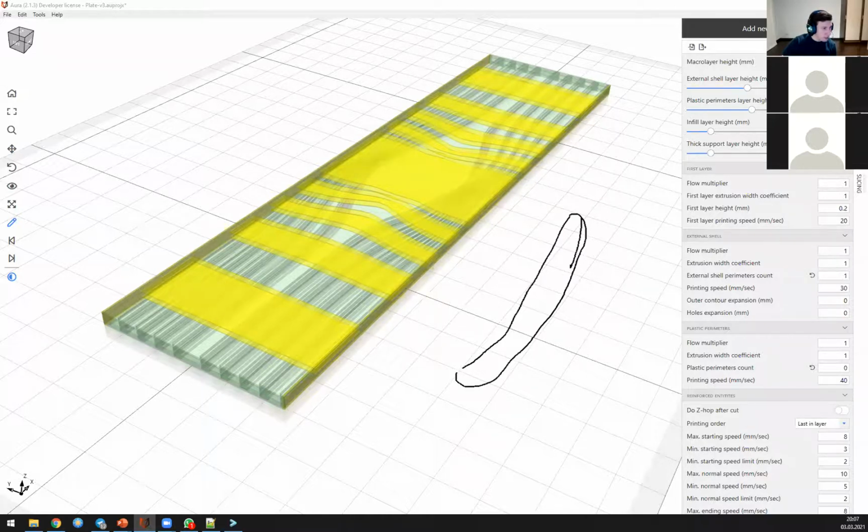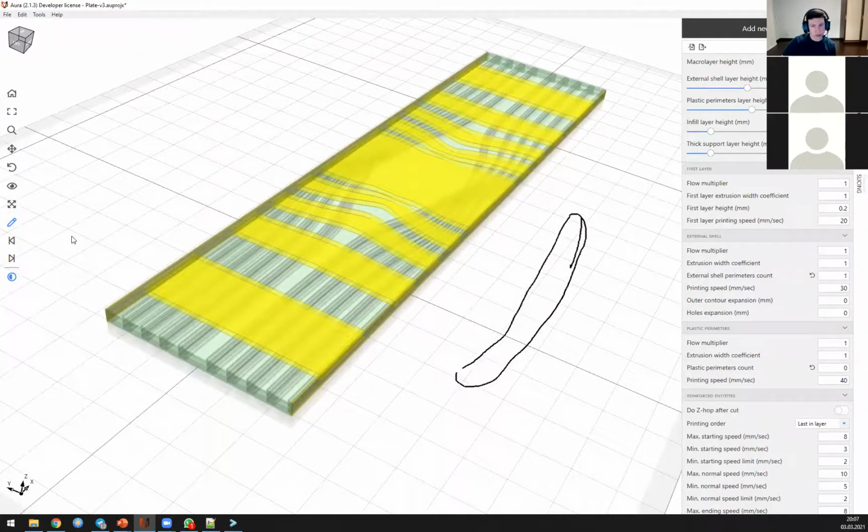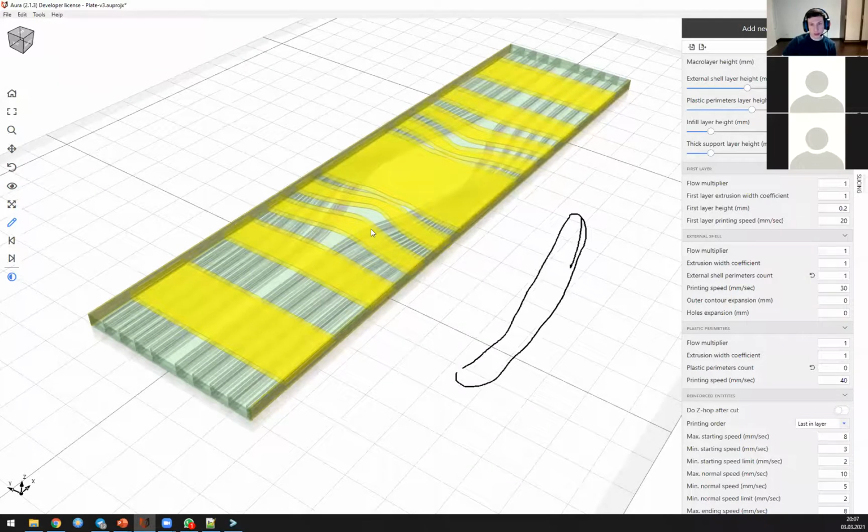How do you simulate the rectilinear path infill in an FEM software? So basically, you can use two approaches. You can fill the internal volume with some grid, like with plates that will form a grid, or you can use something like solid elements. And for the solid elements, you can apply some effective mechanical properties. So if you know the density and the directions of the ribs inside the infill, and of course, if you know the material properties, you can calculate the effective mechanical properties of such a grid, including rectilinear infill or grid infill or isogrid infill. So basically for any type of infill, you can calculate.